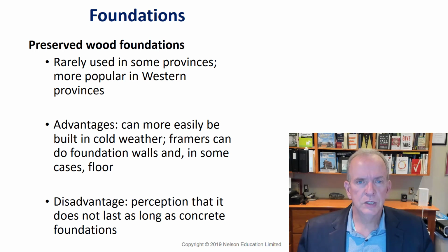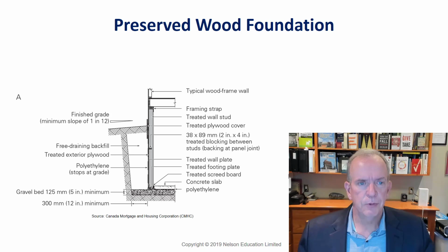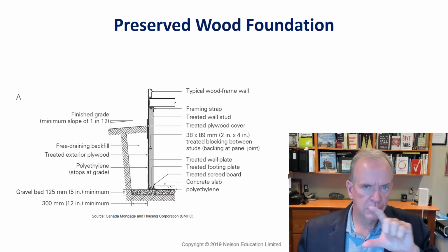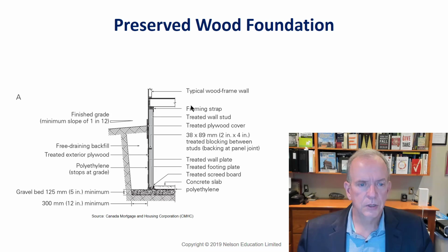Preserved wood foundations use pressure treated wood. They're specially pressure treated. It's not just any pressure treated wood. It has to have a special stamp that I indicate in the book. It's more popular out west. I think here, if you said, oh, I'm going to buy a preserved wood foundation, people would look at you, what, wood below ground? But it has been around for 50 years or more, so it has proven itself.